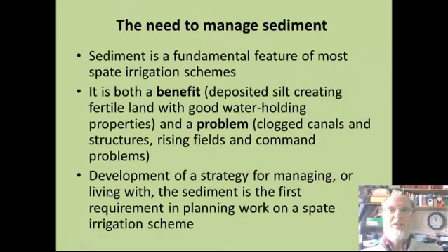We'll start by discussing the need to manage sediment. Sediment is a fundamental feature of most spate irrigation schemes. It is both a benefit, because deposited sediment creates fertile land with good water holding properties, and a problem, because of clogged canals and structures, rising fields and command levels. Therefore, development of a strategy for managing or living with the sediment is the first requirement in planning work on a spate irrigation scheme.